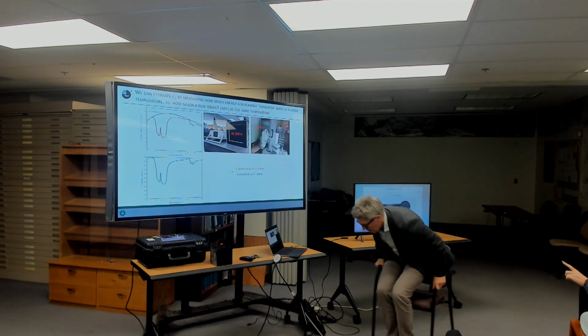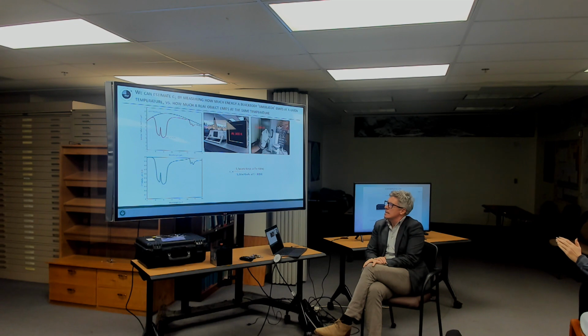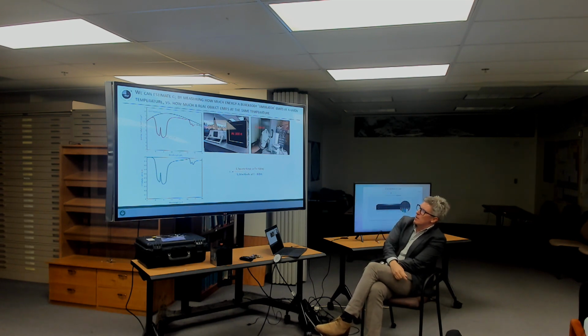So it's saying like at that specific wavelength, it's 40% of what a black body would be emitting? Yeah. Okay. Yeah, 40% is efficient. And then on the top curve there, you can see where the curves overlap, it's basically exhibiting black body behavior. It could never be higher, right? Because it couldn't emit more than a black body because that would be impossible. Sometimes when you make these measurements, it's a little bit over 1, but that's just the experimental error, noise in the sensor, whatever.